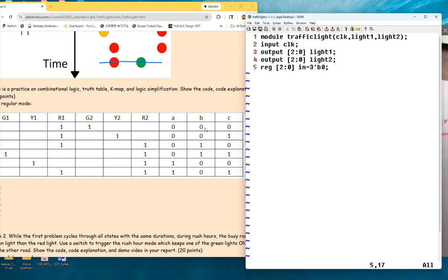And because we want to set a timer, it has to count to a certain number and then add a 1 to it, right? So we need a count max, and we're expecting the light to change every 1 second. So the count max should be 100 mega, and it's a constant, shouldn't be changed. There should be a parameter, and let's call it count max. We usually do 32 bits, and decimal wise, it's going to be 100 mega, 100 and 6 zeros.